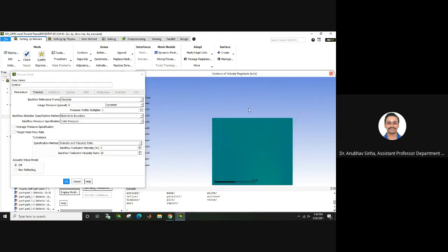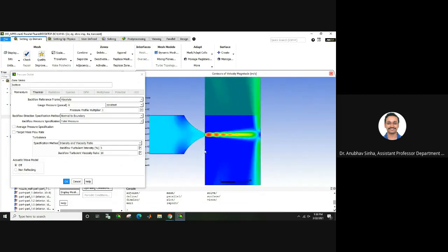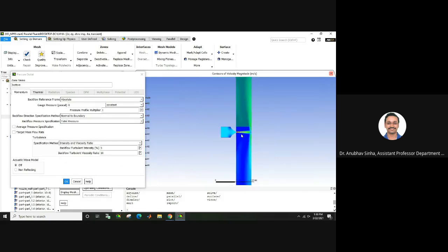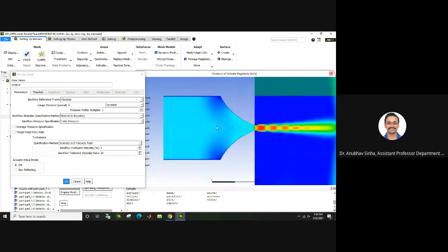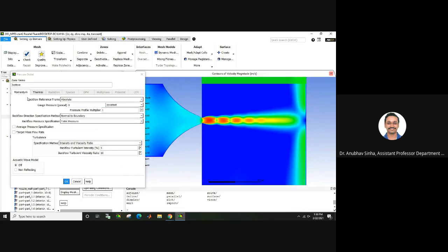This will be decided on what geometry and what configuration you are using. This is particularly relevant for this particular case. So we have a pressure outlet at this location which I have just shown. I don't know why this keeps getting selected. Anyways, the pressure boundary condition will have zero gauge pressure. It means it is at atmospheric pressure. That's all I wanted to keep here.